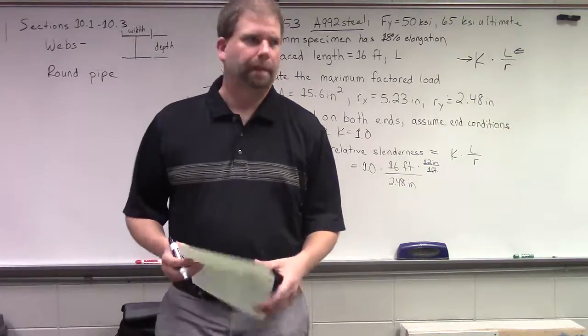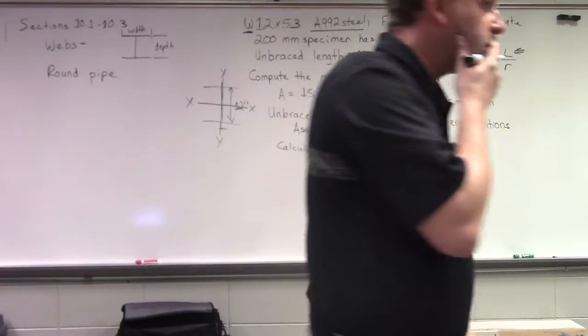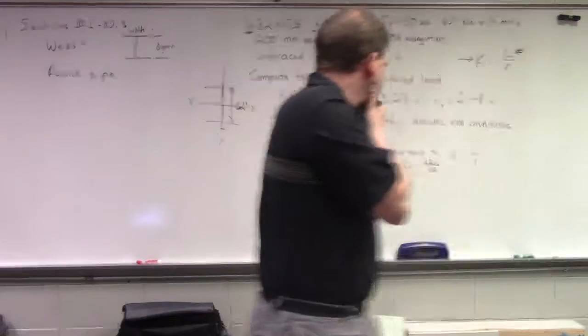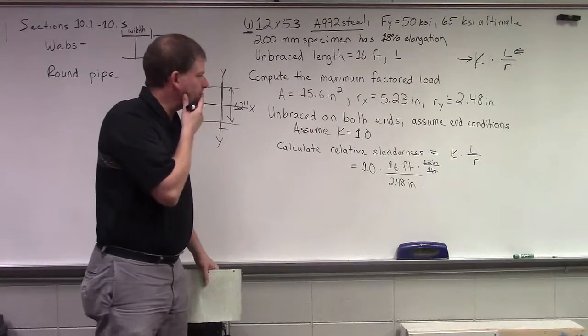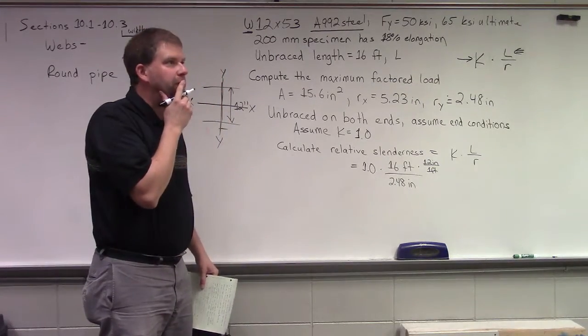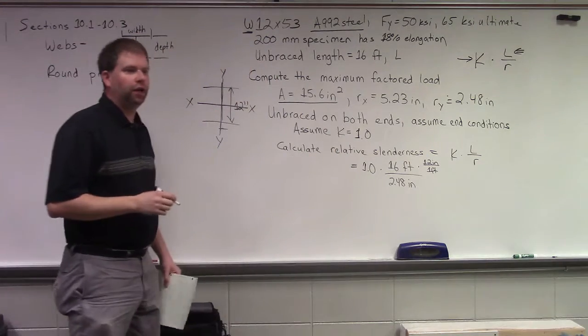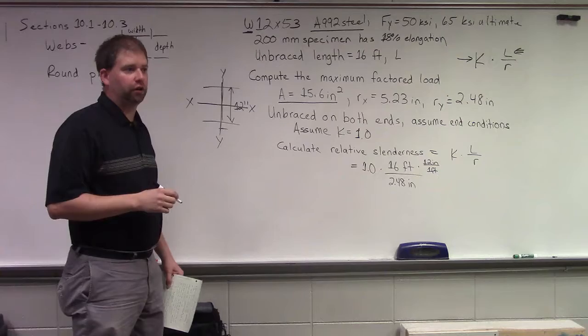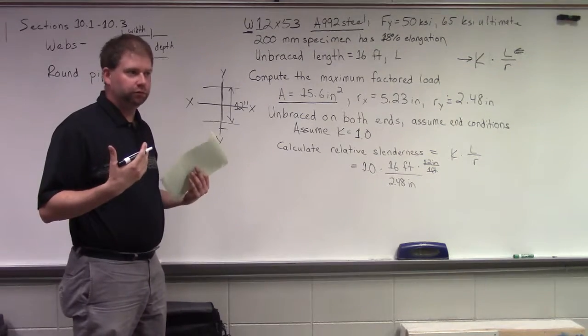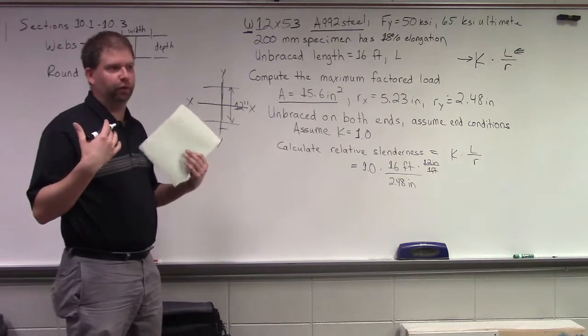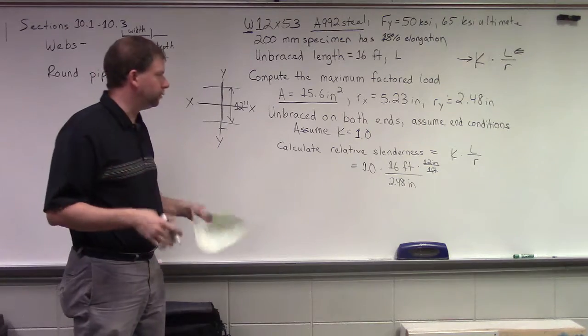But the next step that would matter, is that all in inches? Because that gives you your Fc. Well, in your next step, you're just using your area, and you're going to use a critical unfactored stress that you just get out of the table. The number that comes out of the table is in psi. Okay.